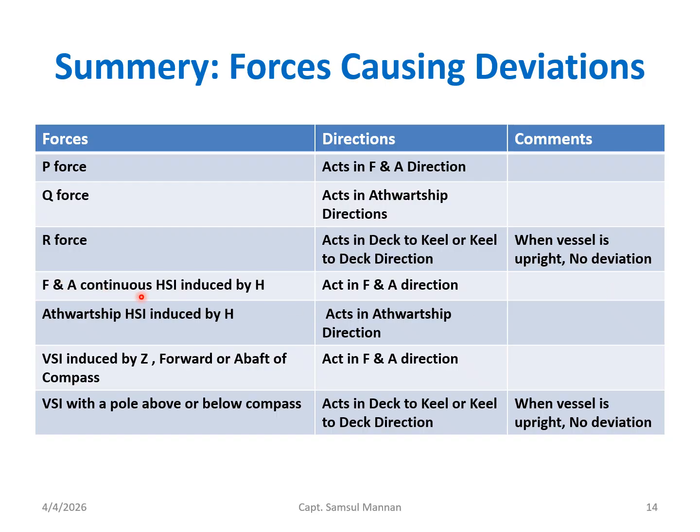Fore and aft continuous HSI induced by H acts in a fore and aft direction, and when the vessel is on a 045 degree or 225 degree course, that means when the fore and aft continuous HSI is partially induced, that time it will have some impact. Athwartship continuous HSI acts in the athwartship direction, and same as fore and aft continuous HSI, when it is partially induced, it will have some impact on our compass needle.